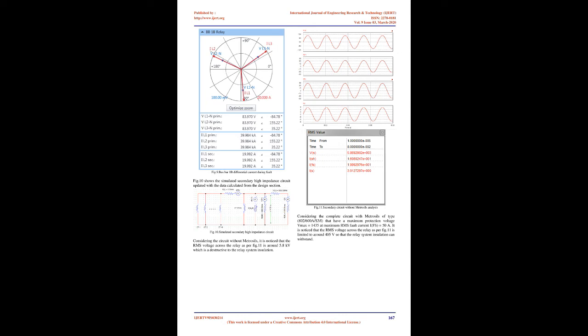V. High impedance differential DC schematic. Typically there are 5 protective relays: 4 relays for the discriminative zones to protect the busbar segments, 1A, 1B, 2A and 2B, acting as a main protection, and 1 relay for the check zone to protect the busbar as a single piece, acting as a backup protection. Each protection has an in/out facility to put the relay in service or out of service, a CT supervision relay that could be healthy or unhealthy,